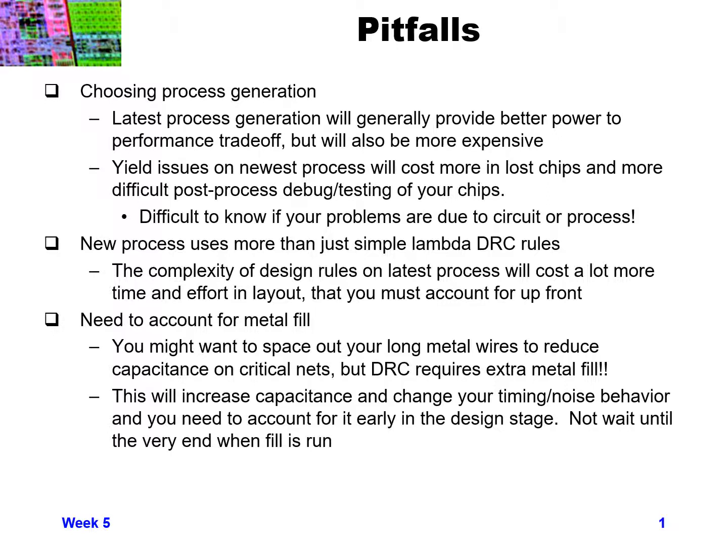You might see 2x the number of design rules. And so there are new design rules that you had never seen before, never heard of before, that you need to design to. It's going to cost you a lot more time and effort doing your layout, and you should make sure to be aware of that and account for that up front when you switch to a new process technology.